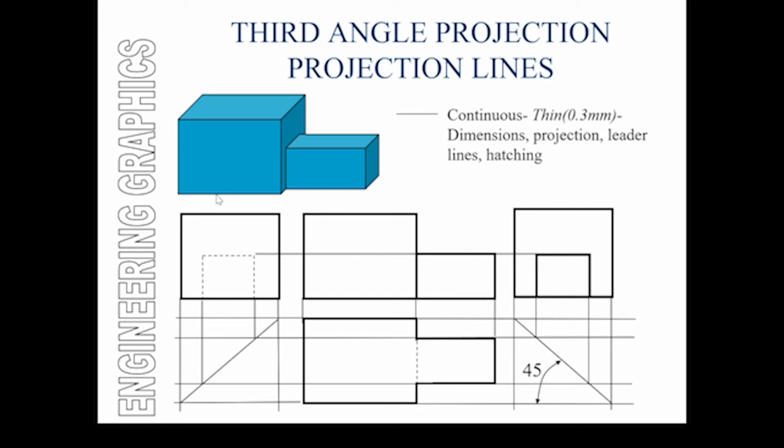Okay, so imagine you're shining a torch at it and the light is traveling through. When you shine the torch, probably the first face you're going to hit is going to be this face here, and the light is traveling really slow. So you're going to see that, right? So what I tend to do is draw that as the first detail in solid visible line, basically a continuous thick line for the visible edge.